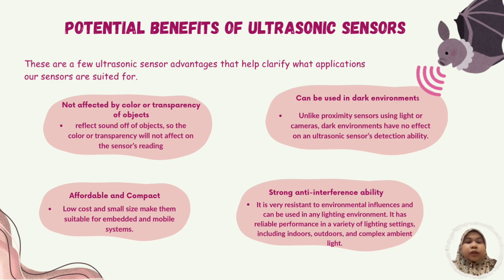Second, can be used in dark environments. Unlike proximity sensors using light or cameras, dark environments have no effect on an ultrasonic sensor's detection ability. Third, affordable and compact. Low cost and small size make them suitable for embedded and mobile systems.